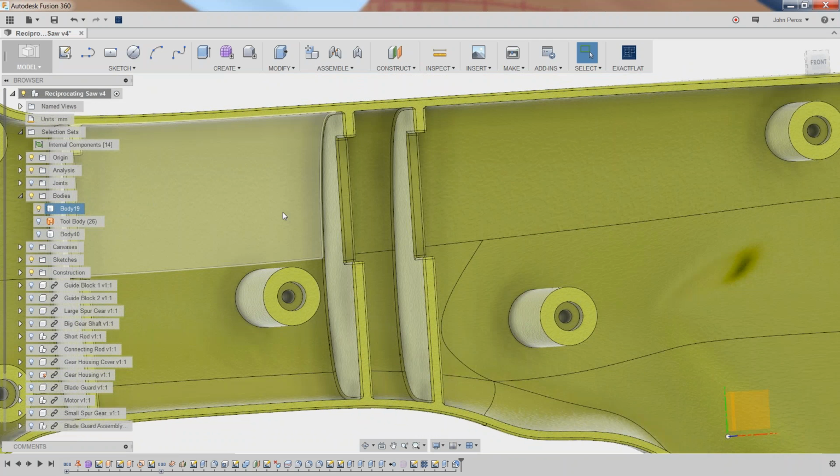But back when I was in engineering school, nobody told me that you can't have fillets on drafted faces. In fact, fillets are very common on drafted faces. So there's no engineering reason that I have to do draft first. That's a CAD system reason telling me I have to do draft first. And that's a rule that I need to know if I'm expected to utilize that CAD system properly. That's not the case in Fusion. Again, one of the reasons that doing a rewrite of a CAD system is so nice is that we can take some of those strange things out and we can make it behave properly.